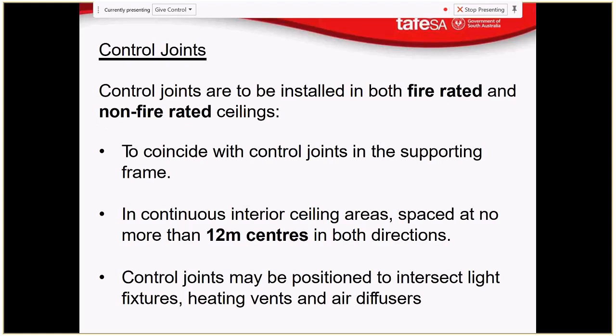You'll hear the term control joint used in so many things, particularly in concrete slabs, like for industrial warehouses. We've got really big long slabs. We know that it's going to crack somewhere. We want to ensure that cracking happens in a specified place. In masonry walls, every 6 metres or so, we have to have a control joint. Same thing, same terminology.